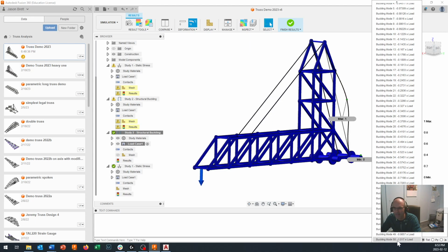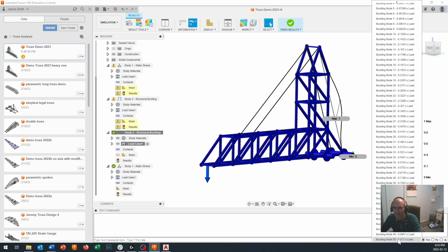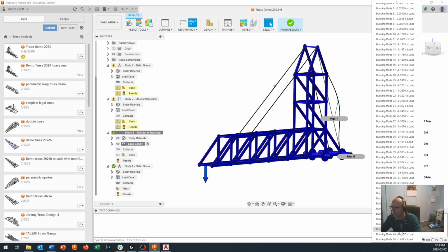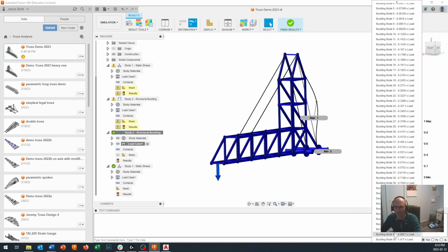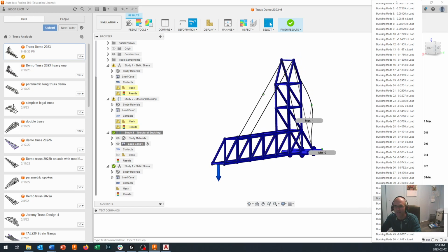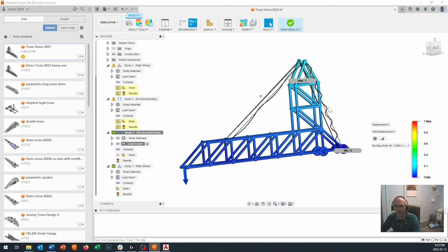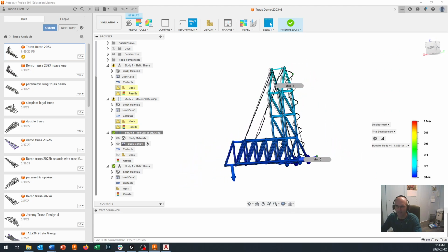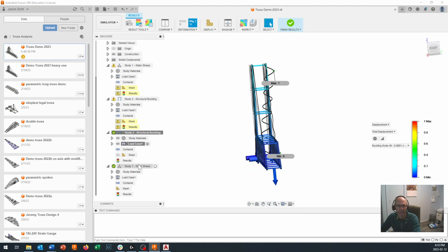And you can see that I've made it all the way up to -1, and that one's not buckling right on there. So this structure is going to hold up, but I just want to see what it's going to look like. That structure is going to need to be redone. I need more modes of failure because these modes of failure are all in the negative, and that's not what I'm looking for. So I'm going to just change my structural buckling study here.